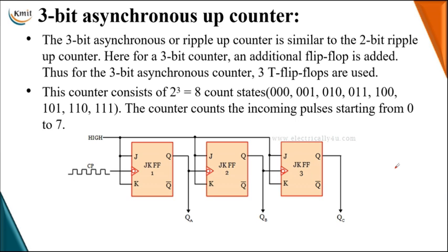As in your 2-bit counter, this is an up count sequence. When you observe the difference between successive states, it is equal to logical 1, which is a plus 1, hence it becomes the up count sequence. As we need to design a ripple counter, we have to prefer the toggle state, or if you use the JK flip-flop, it has to function in toggle mode.